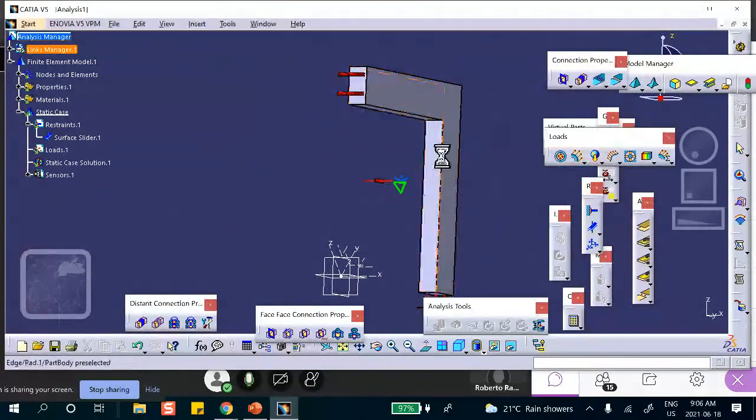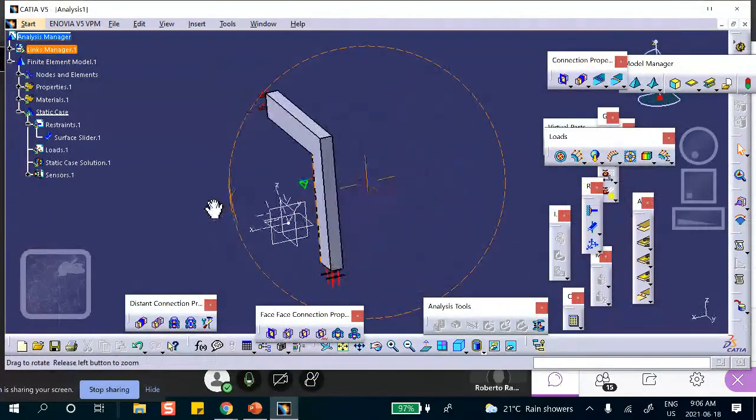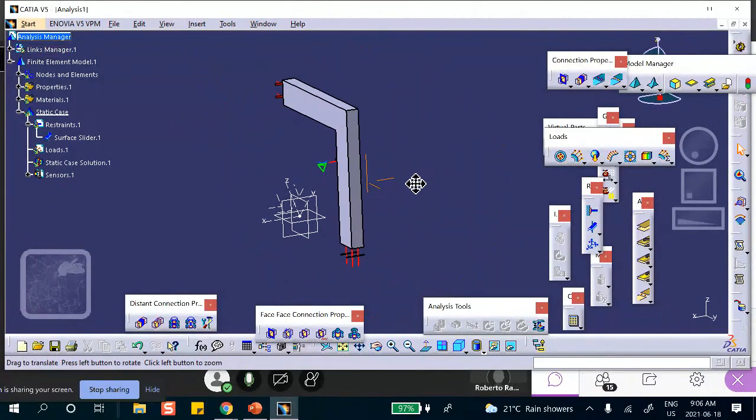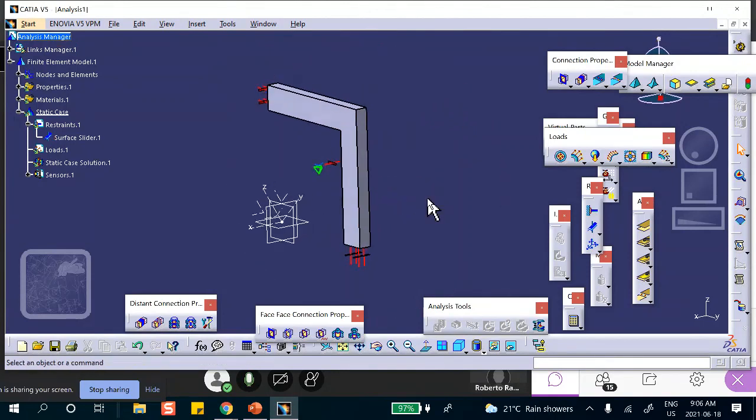By doing this, you're saying, I don't care about the loads that may buckle this thing out of plane. Just give me the in-plane ones. Okay? That may or may not be okay. If you know what you're doing, maybe okay. If not, you're in trouble. Because you're going to ignore those buckling loads, which may be lower than what you get here. And then when you fully load the structure, it will buckle out of plane at a much lower load than what this guy told you.